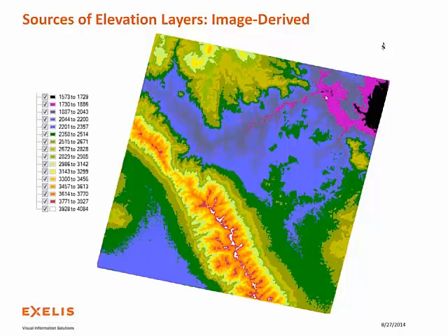And the other thing to note is when performing this type of DEM extraction, it can take a lot of time. There are mechanisms to decrease the resolution, not of the DEM that you're extracting, but it can be downsampled so that it doesn't make as many triangles in the triangulation process, which saves a lot of time and disk space. If you don't need the high resolution requirement, there are ways to refine the DEM in such a way that you can process it quicker while maintaining some accuracy and saving disk space.